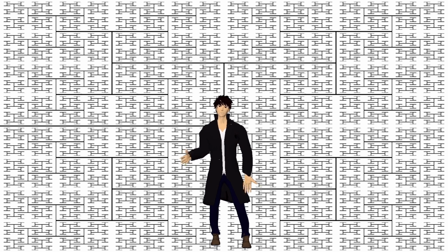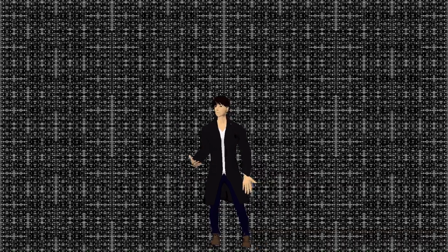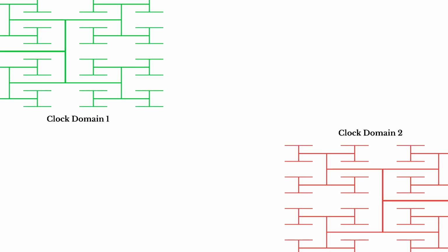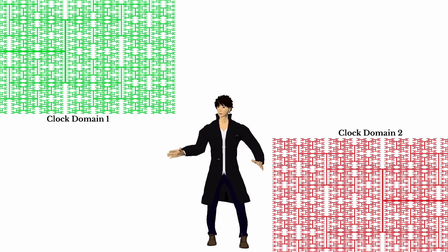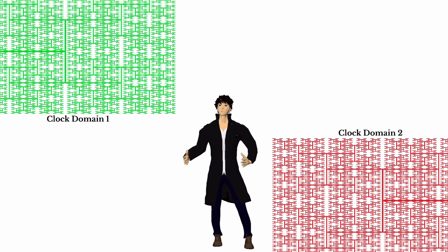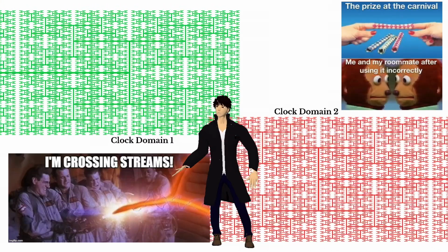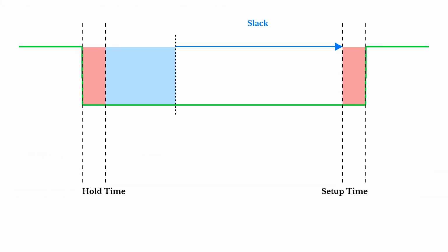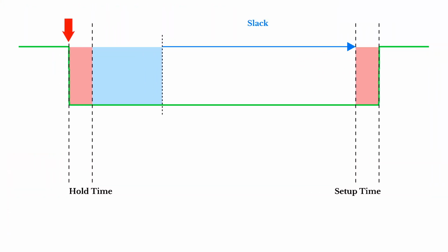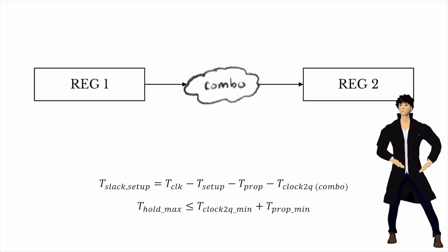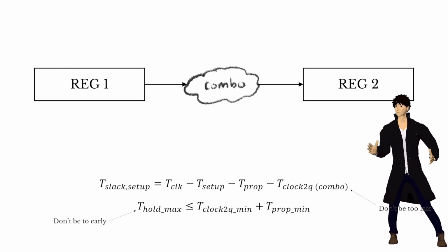Managing multiple clocks is less straightforward. If your logic doesn't touch something with a different clock, you're fine. The problems occur because they frequently do. Remember that setup window I kept going on about? The signal gets clocked in at the source register, held for some amount of time, and then has to propagate quickly enough to be accepted by the destination register. We had a nice, simple equation for it.